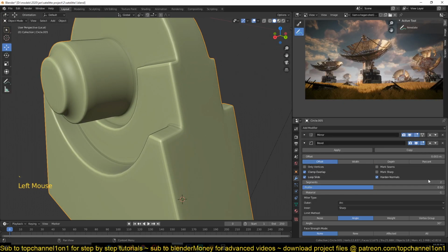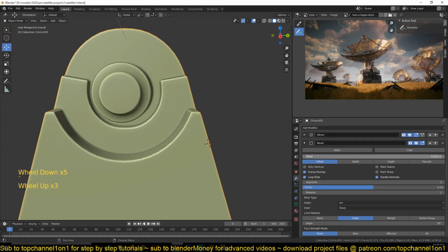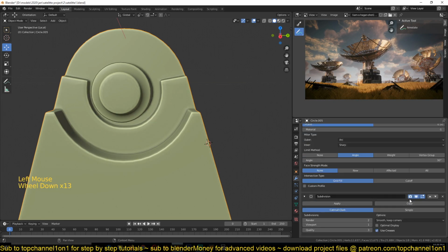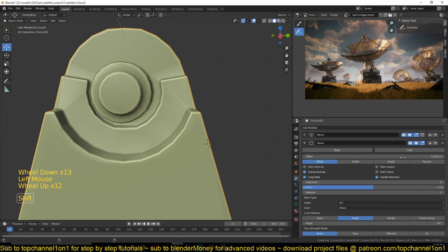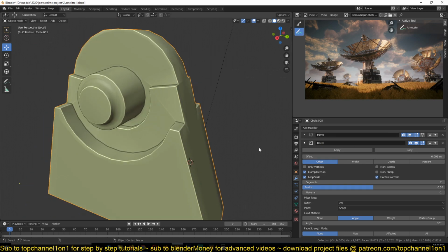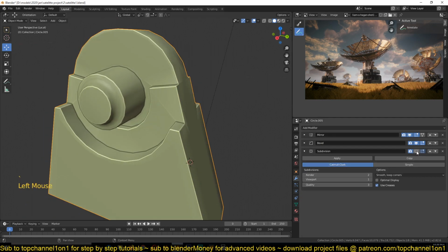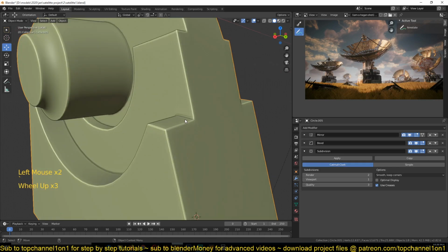And if you want, you can also increase the bevel segments again to make this loop tighter, or you can reduce these segments. Let me first reduce the subdivisions and reduce the offset here, something tighter, and now you will get a sharper subdivision.